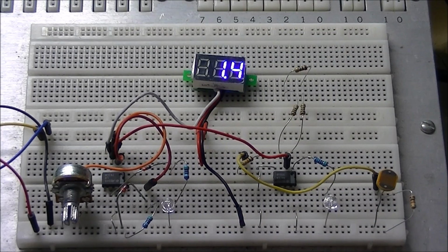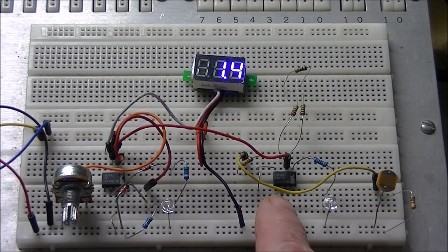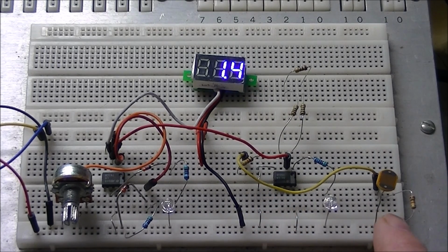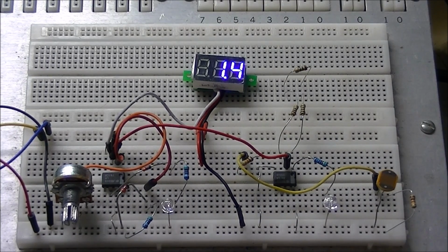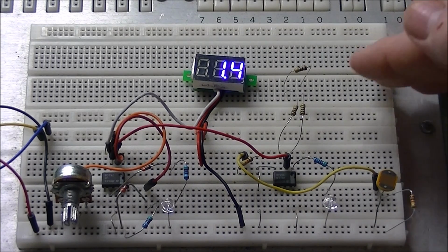I had to cut the overhead light down for this next part of the experiment, but it will become obvious why I did this. If we look on the right side of the page, there is my LM358 op-amp. But over here is a cadmium sulfide photocell, or what they call a photoresistor, with another resistor in series. This time I'm using one of the inputs on the op-amp to come from this photocell resistor combination. And depending on where I adjust this pot, if I block the light from the photocell,